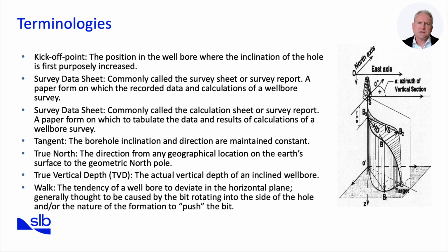In harder formations, the bit may naturally walk to one side due to unequal formation hardness, bit design, or side forces. Engineers analyze walk tendencies to predict and correct unintended deviations, especially in horizontal drilling, where staying within a narrow reservoir window is critical.